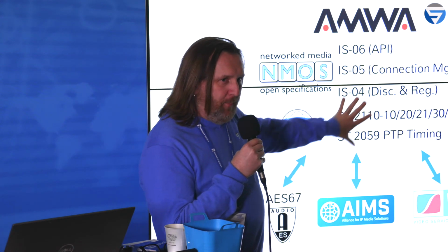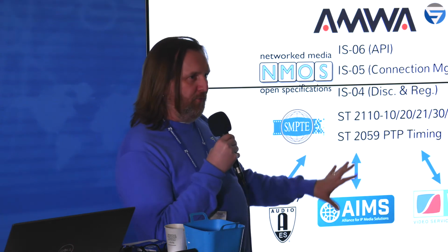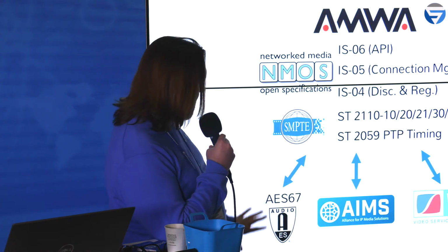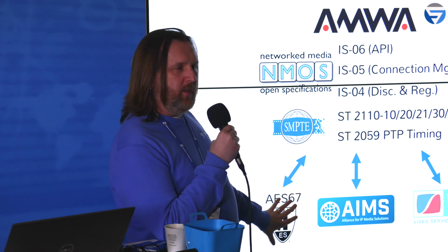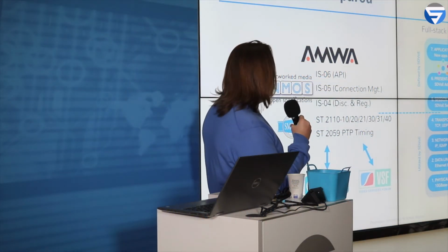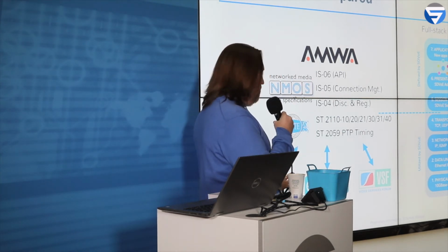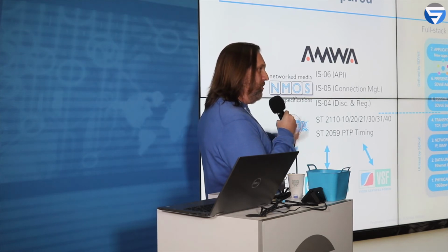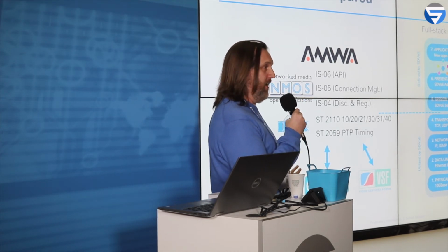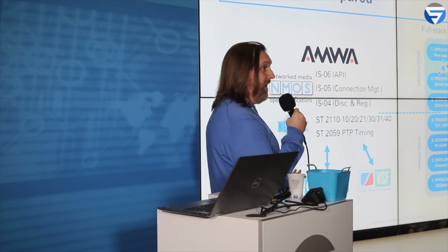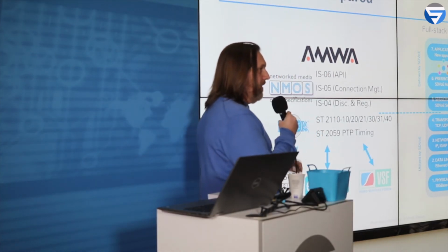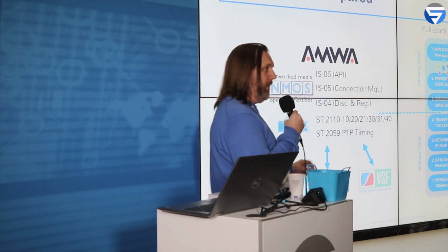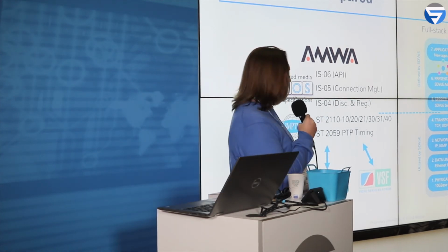When you start to dig deep into all these standards, you realize there are certain influences from other organizations. For example, AES wants AES67 to be the audio stream of choice when implementing 2110. However, when you look at this AES67 model that's used in 2110, it's a constrained set of AES67. It's not AES67 as is. Similarly, you've got organizations like AIMS who are trying to shape the way you use these standards to make them work in specific flows, as I said earlier, specific broadcast workflows.